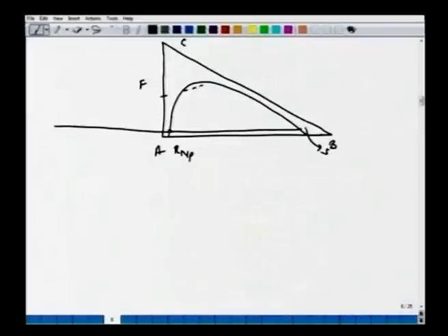This is a tie line which extends through F, and it meets the difference point, or it meets this line right here. Now we said that in general it's possible that all the tie lines, if you extend them, will be intersecting this line closer to this R, like this.